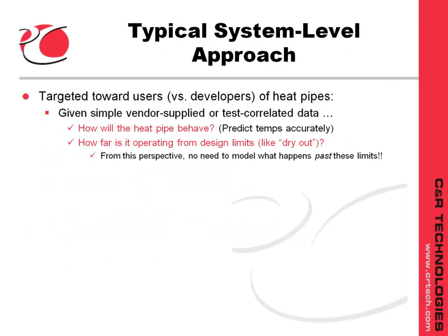So, how should you model heat pipes from a user's perspective? The user needs to know how the pipe behaves. What temperatures will equipment, plates, and radiators arrive at when they're adjacent to this heat pipe, and how much margin is available compared to the transport limits.